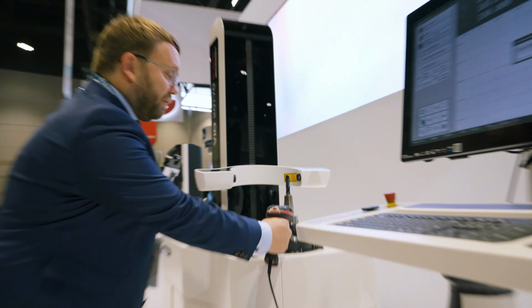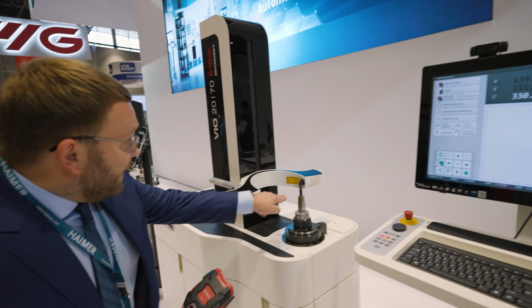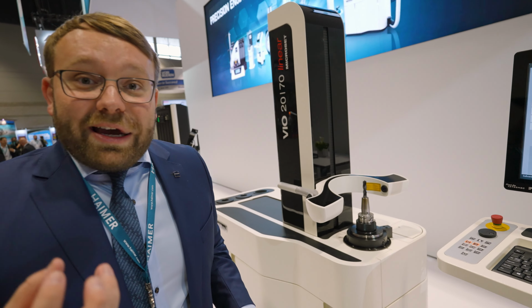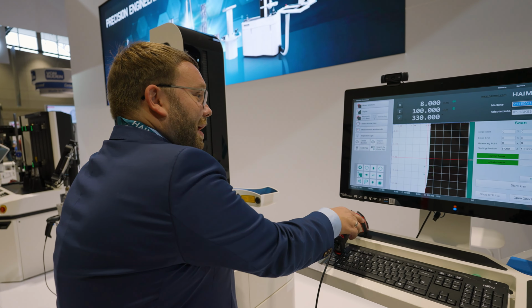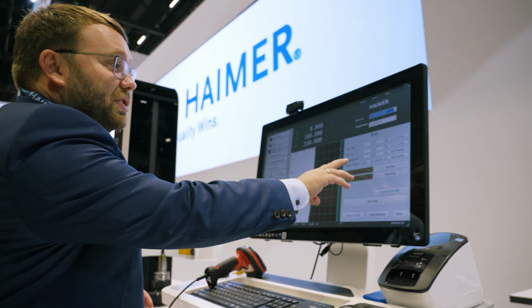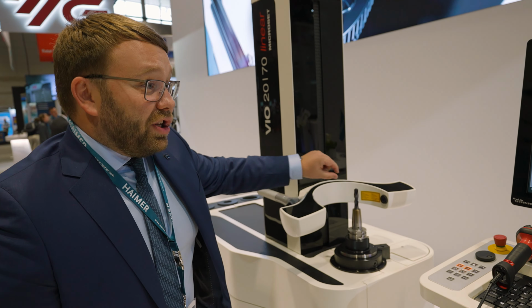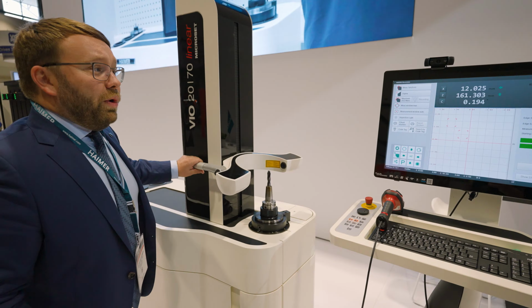That's an automatic presetter. That's our Violinear series, fully automatic. It actually works very easy. All of the presetters have our data in the database, so I just have to scan here. It automatically adjusts. So we are starting the scanning process where it actually matters. I will go up and set here. I just have to fill out one point. We want to know the cutting edge data. We want to know where the actual cut is happening.